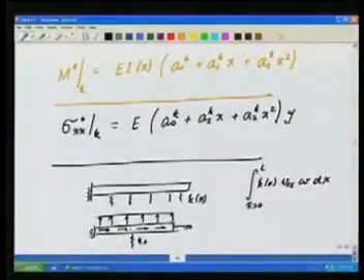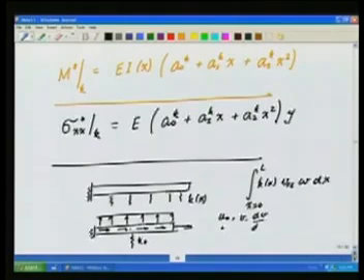In this case we will also have the axial displacement. The axial displacement will give me a second order differential equation, the transverse will give me a beam, which is the fourth order differential equation. So we can combine the two and solve the problem. In this case, at every node we will have u0, v and dv dx as our unknowns. So there will be 3 unknowns, which is not a big problem. Once we have understood how to do these things, then we can handle this. So essentially, in one dimensional problems this is all we are going to look at.